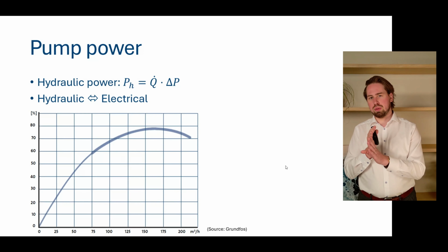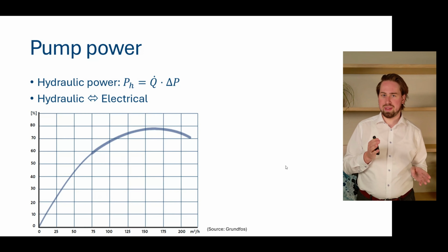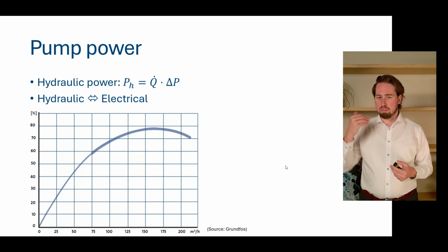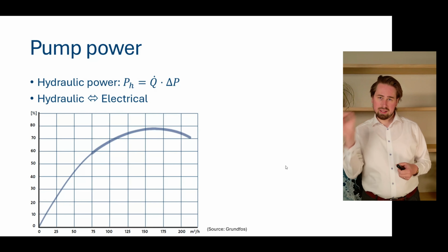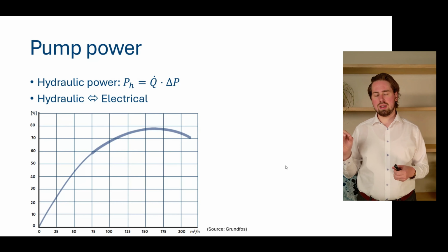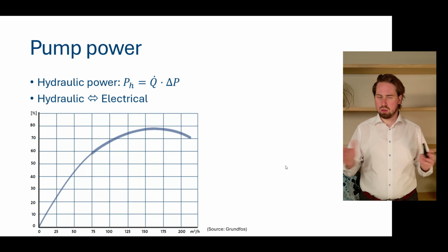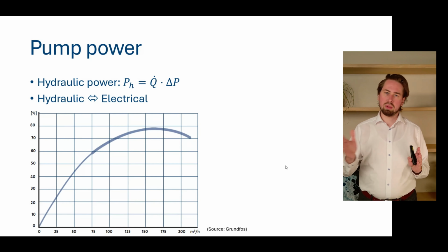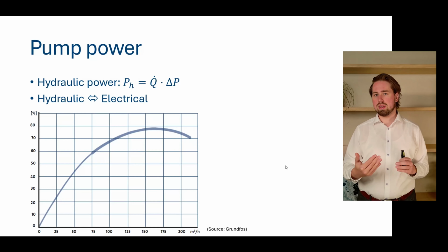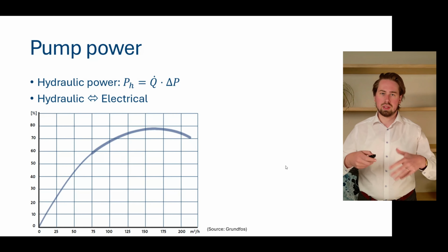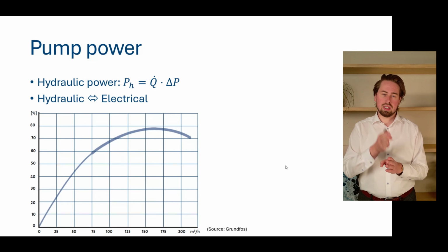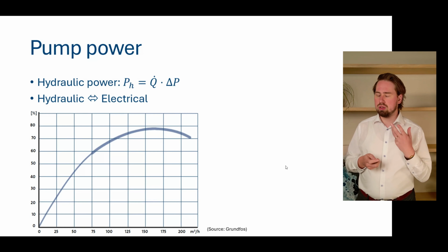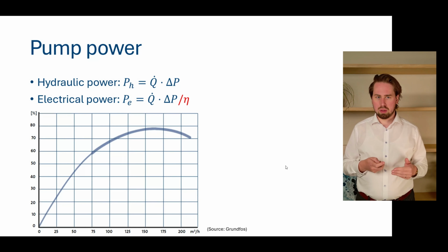But then you know that most of the year, you will actually be working at a lower efficiency. Whereas if you say, okay, let's design our pump with the maximum flow rate at the very end of this graph, not the highest efficiency, but then you know that when you're playing around with your flow rate, it varies over time, that when you go into part load regime, your pump will have a higher efficiency. Which is interesting because most of the time, most hours, you will be working in this region of a higher efficiency. And that's interesting to consider when we're talking about pump power.